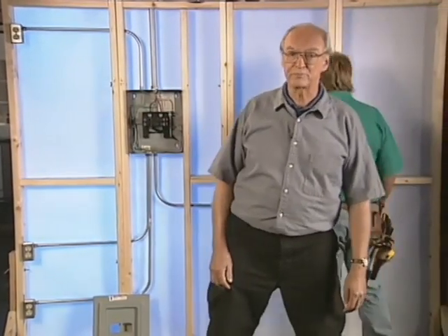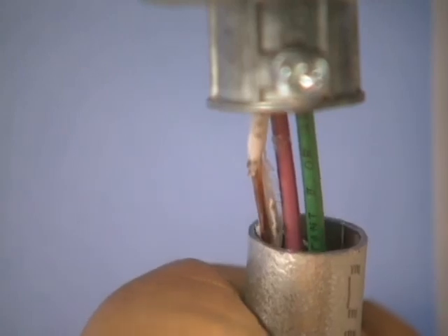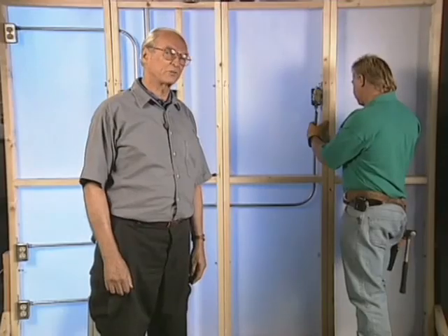Sometimes a neutral to ground error is found out in the circuit. Here is an example of such an error. The neutral is grounded because the neutral wire is nicked. Sometimes the sharp edges of a fluorescent light fixture mounted without the correct bushings will cut through the neutral insulation.